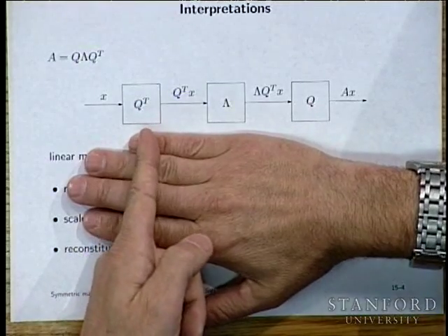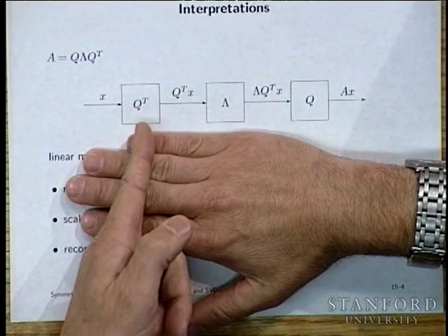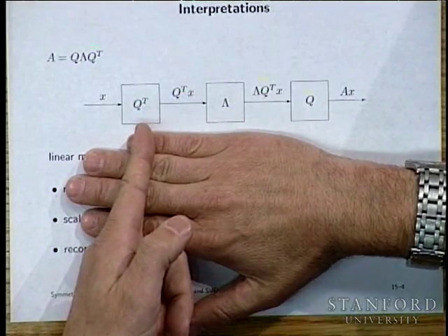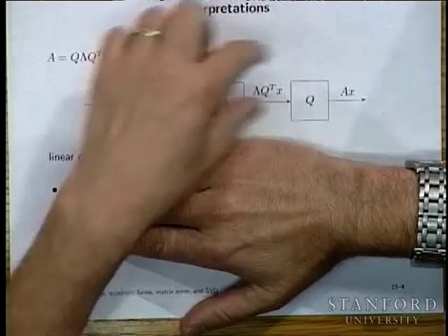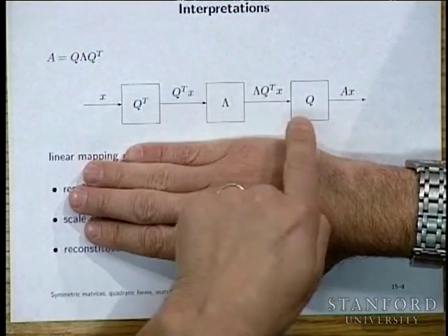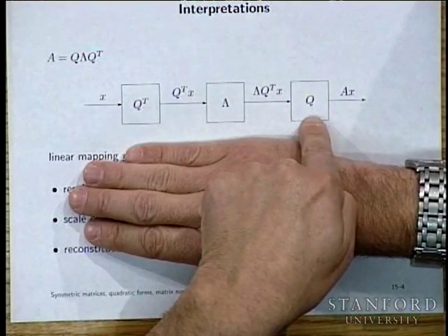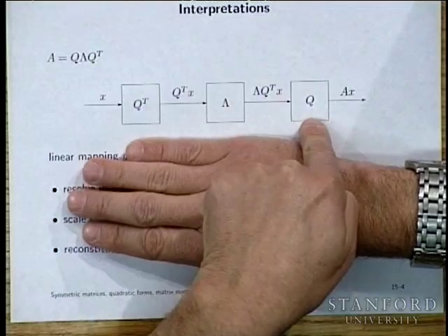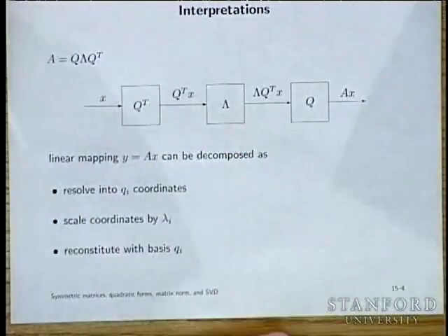In JPEG, or at least in one of the older standards, you take 8x8 blocks of pixels, you form a DCT transformation, and then in fact you don't multiply here. What you do is quantize in the middle, and then you transmit these, and then it's reconstituted when you decode the image. Okay, so pictures like this are all around you, widely used, and so on.